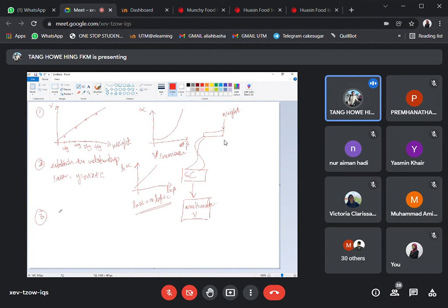And the third step will be, now we are going to measure the voltage. Okay, instead of having this kind of graph, now, based on the relationship, we try to do the actual measurement. So in this case, we reverse it. This is actually the weight, and now the input will be the voltage. All right, so just by measuring the voltage and relying on this relationship, we are able to determine the weight. For example, here I get a voltage which is somewhere around here, and therefore according to the relationship, I should get this weight.